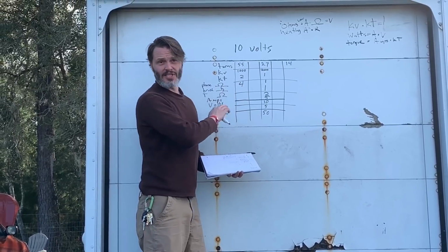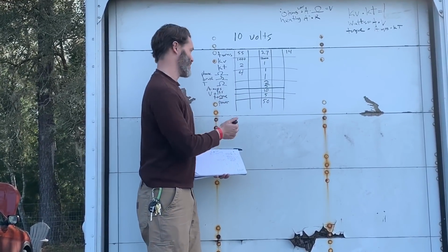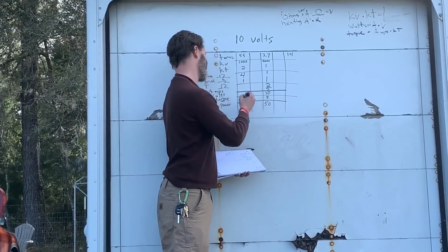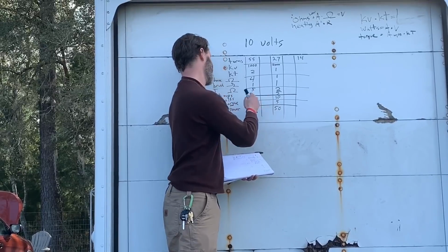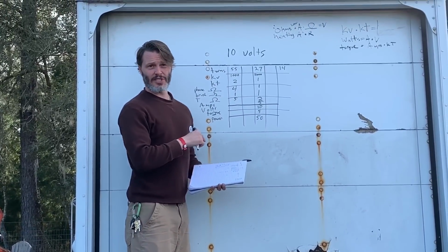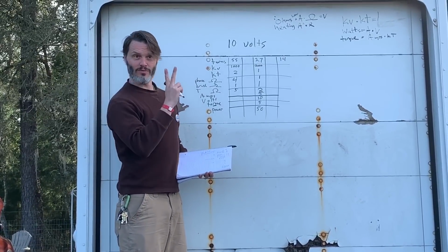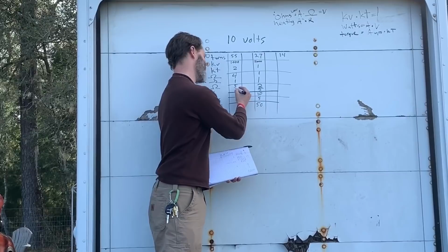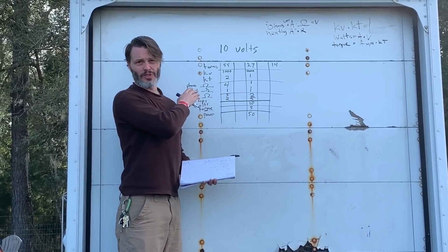Our brush resistance is going to stay the same. We're going to assume that the brushes are the same brushes on all these units, so we're still at 1 ohm for that. Total for our motor now is 5 ohms resistance. What is it going to draw on the amperage now? 5 ohms resistance, we're putting 10 volts to it: 2. It's only going to pull 2 amps now for a 55-turn motor. And by the way, these are actually pretty close to real-world numbers.